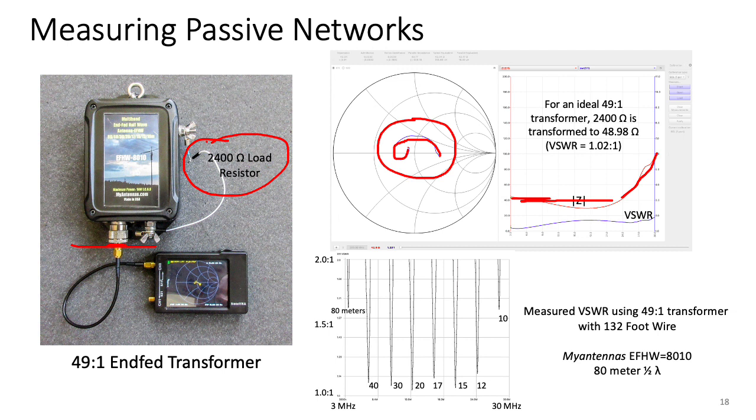Now, a couple of things to point out. One is at the higher frequencies, this little piece of wire turns out to be more and more problematic in terms of its inductance. So if I wanted to do this very, very carefully, I would have used a very thick braid here to minimize the inductive reactance that I would have at the higher frequencies. So this climb that you see here may not be due to the transformer.